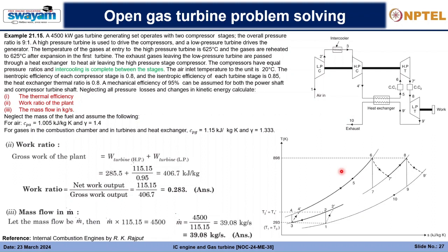The main motive is that we need to gain some confidence in solving problems related to gas turbines. And now I hope that we are a little bit more confident than before in solving open cycle gas turbine problems. We now know how to utilize the concepts of intercooler, then regenerative cycles by using a heat exchanger, then reheating between two turbine stages.